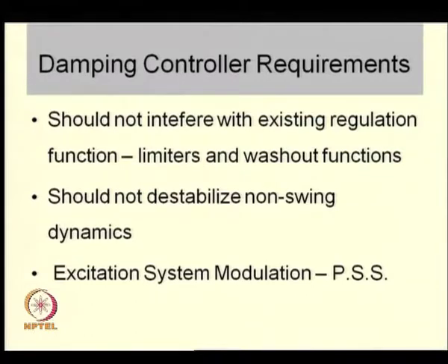The second point, which is very important, is that in steady state, the effect of this augmentation should be minimal. That is, in case you are making a change in the controller, the damping controller output should be 0 in steady state, because it has no function in steady state, it is just trying to stabilize the system. So, a damping controller, or in other words a power system stabilizer, has to augment the existing controller. When I say augment, usually it means that you do not tamper with the existing control system.